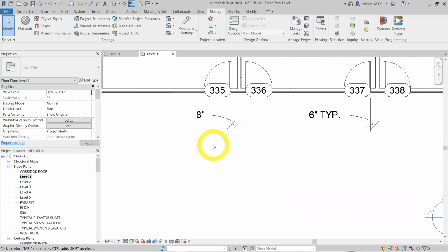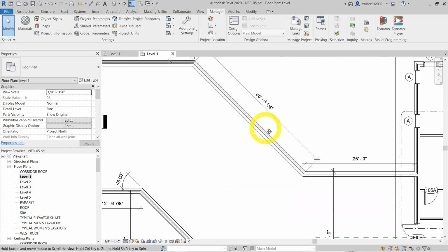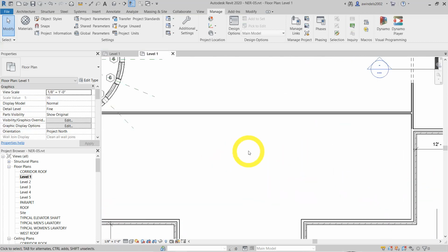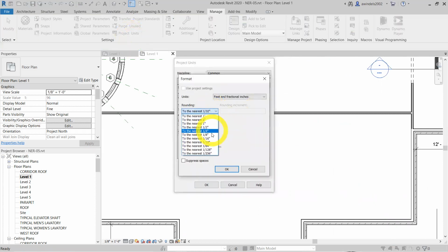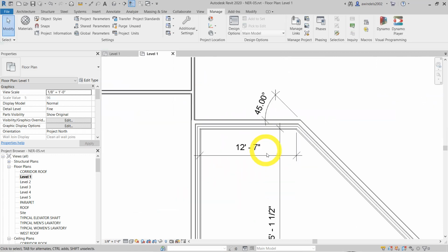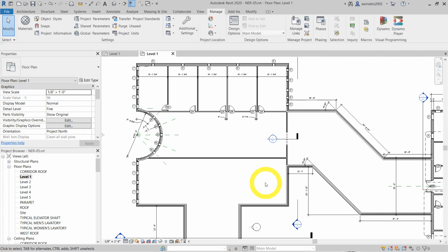We can go back and re-edit. So just that dimension, I think we got them all at the right, the nearest rounding. So we went back there. I want everything to round to the nearest, I don't know, fourth of an inch. Let's do that as well for our annotations. And nothing will be any more precise than that for any dimension.